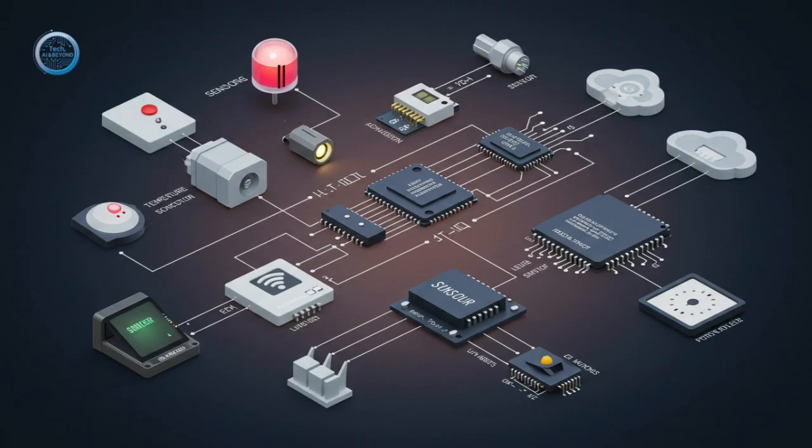Definitely. Then you've got proximity and level sensors. These detect objects nearby without actually touching them. Ultrasonic sensors are a great example. They emit sound pulses and measure the time it takes for the echo to return. You find them in vehicle parking assist systems, helping robots avoid obstacles, and even for measuring the liquid level inside large industrial tanks, giving real-time inventory data. Like sonar, basically. Very much like sonar, yeah.